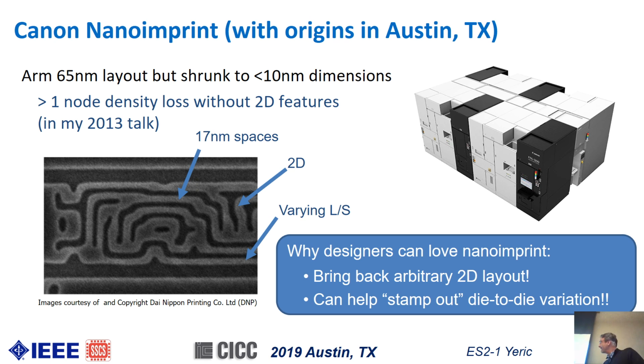And it literally is taking a 3-dimensional mold and pressing it into the photoresist, and miraculously pulling that mold back up without any defects, and doing it so fast on the wafer that it's affordable. It's again kind of science fiction that this could even work. They've been working on it for years and years and years. Canon ended up buying this technology, so you can buy this tool from Canon. It can make these sub 5 nanometer, sub 7 nanometer type of features.